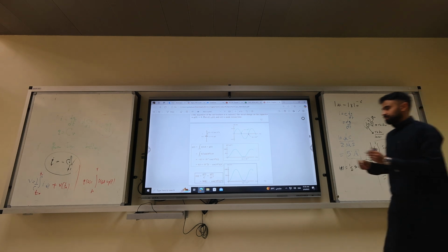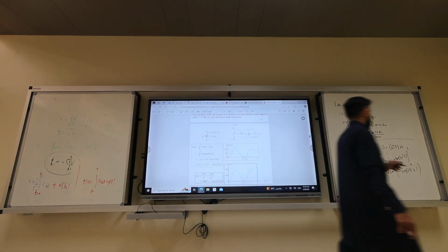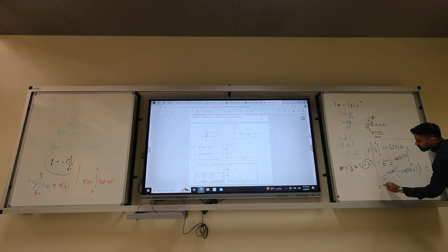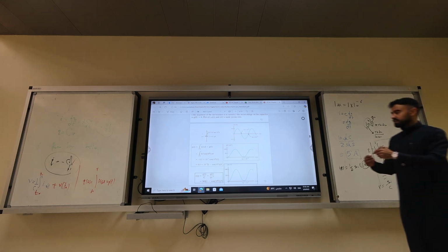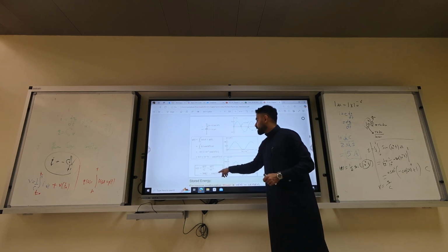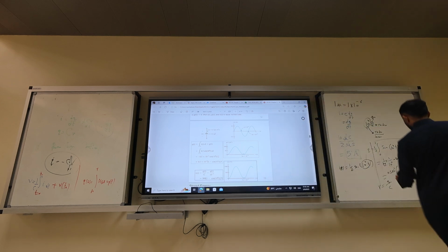And what's the unit? It's coulomb. This is the charge. So this is Q. What is V? V equals, you take the whole number, Q, and divide it by C. So you just divide it by C. And then you will get another number, which is 500 times 1 minus cosine 10 to the power 4 t. You divide it by 10 micro, right?